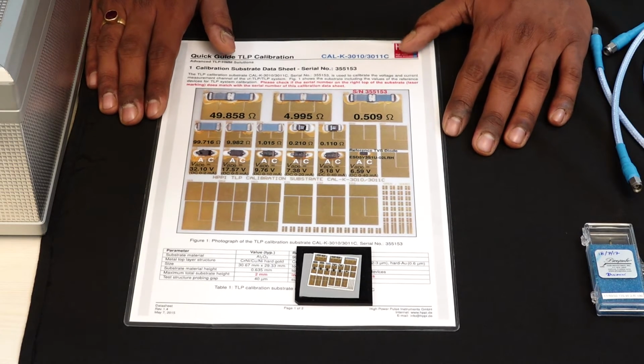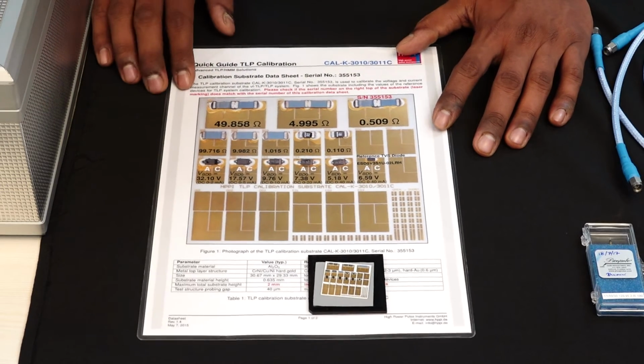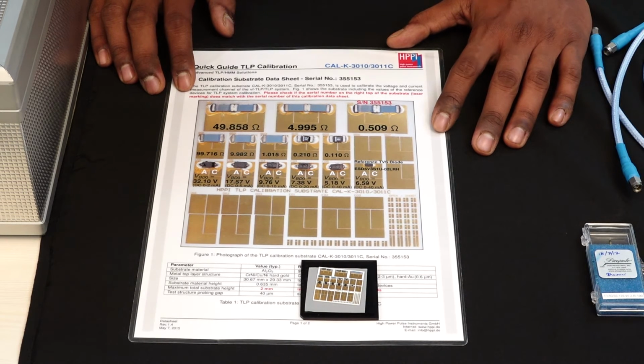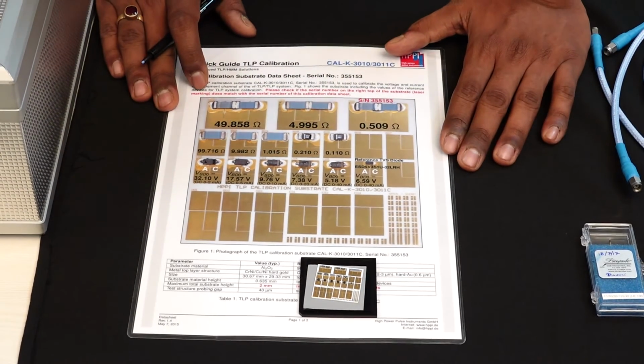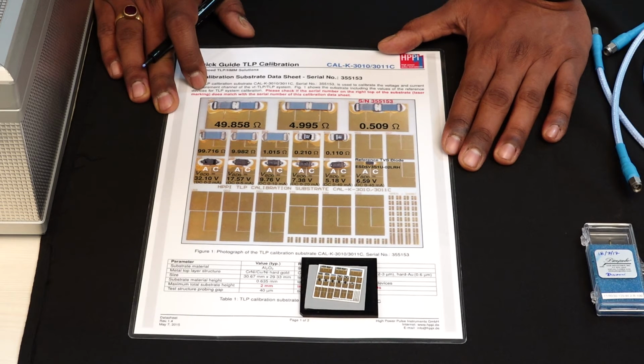Finally, the current channel is calibrated through a resistor that's here in the calibration substrate. These resistors have a certain actual resistance, and then you have a measured resistance, and by comparing these two, you can measure the current factor as well. So that's why this calibration is important. It's a pretty involved process, and I'll talk about it in further detail and show you the calibration steps once we start doing the experimental measurements.